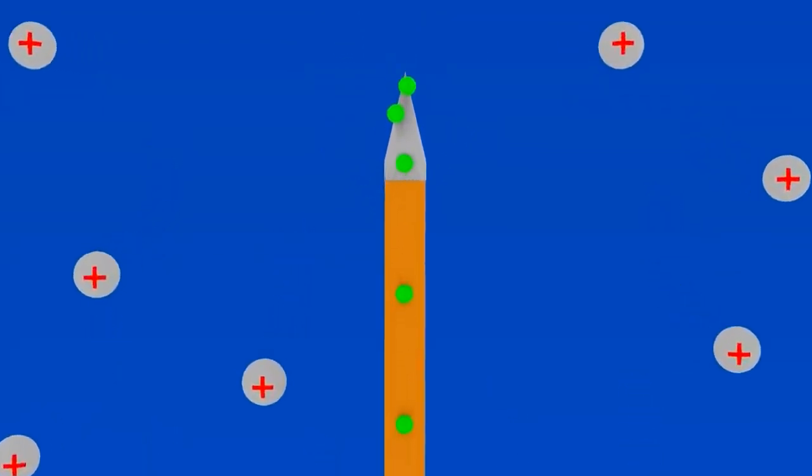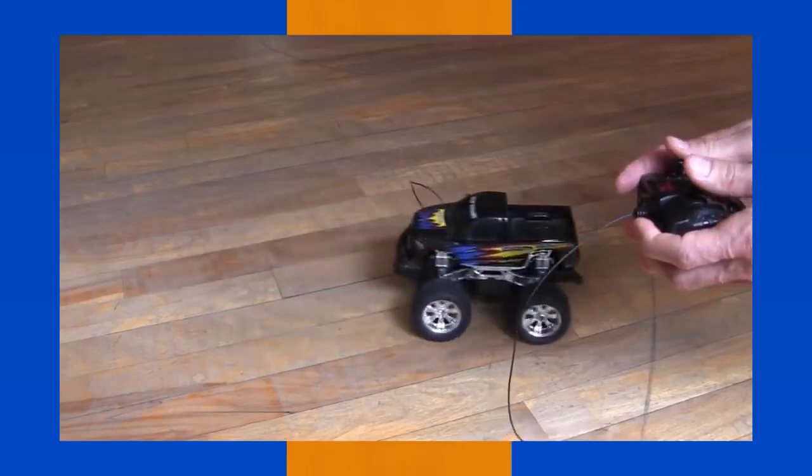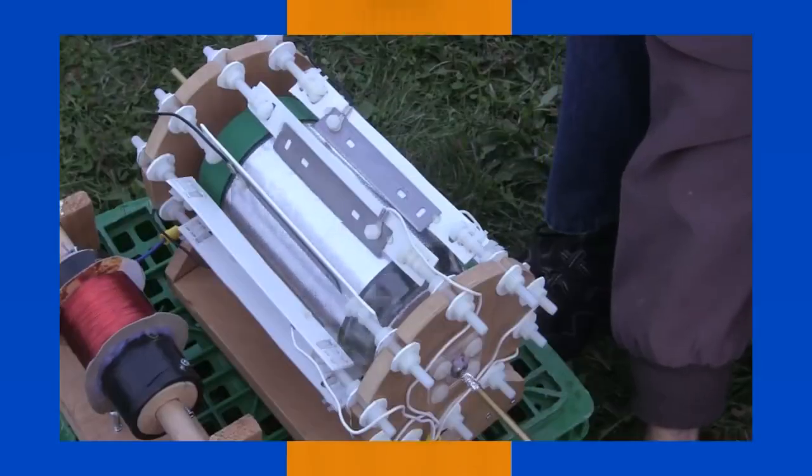The electric current in that electricity is very weak though. We didn't measure it, but from my experience with electrostatics, I'd estimate it in the low microamps, or more likely even lower. That's not enough to turn an electromagnetic motor, one like you use in everyday life, but it is enough to turn an electrostatic motor, like this corona motor.